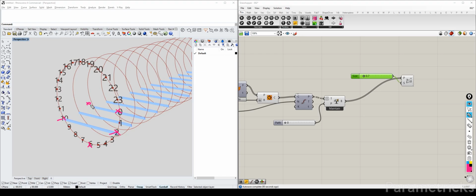What we can do is we can say, hey, I want you to draw a line straight down, and where you intersect, that's where I want the new starting point to be. So then it will be 0, 1, 2, 3, 4. Then it becomes a bit easier for us to predict if we have any changes of our circle. Let's say instead of 24 points we have 48, whatever, then our method will ensure 0 will always start from here instead of somewhere here that we don't know. We simply don't know.